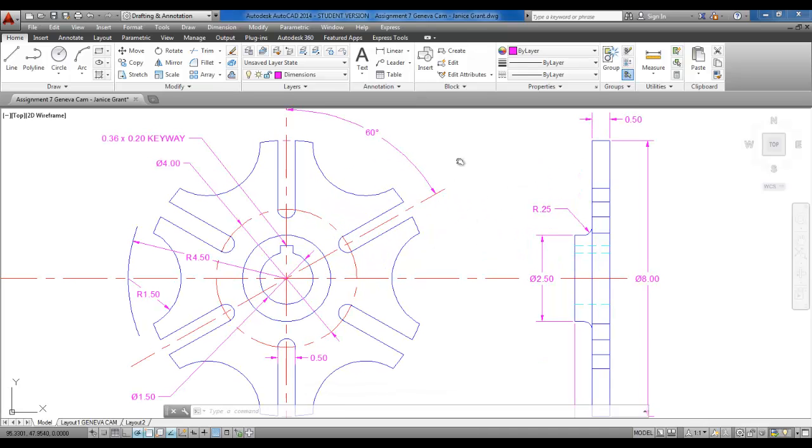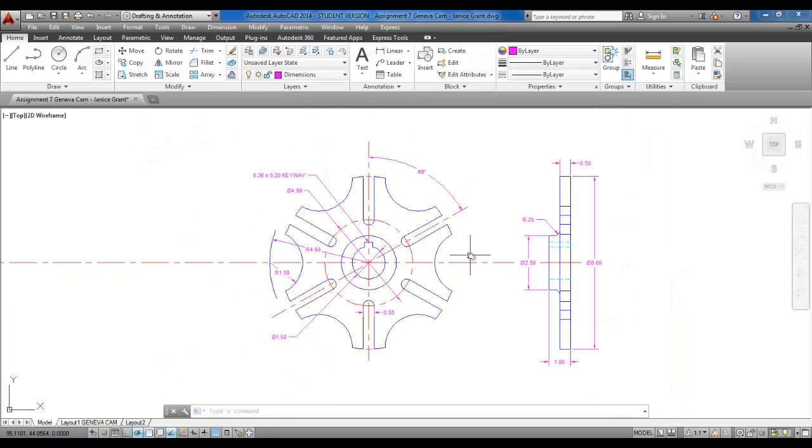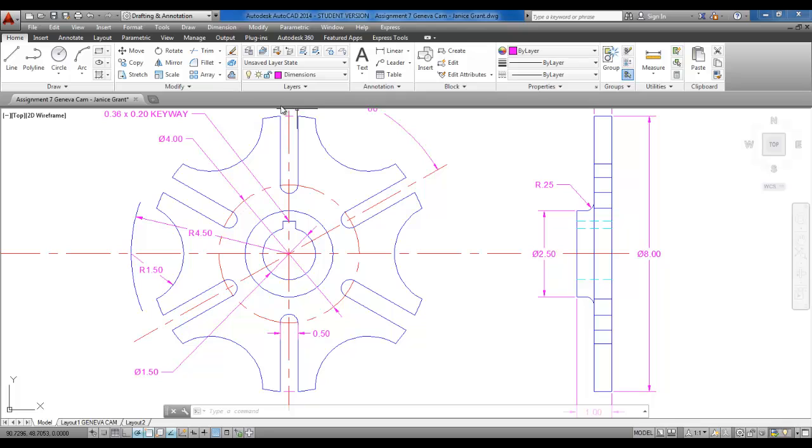So you'll need to probably go back and create another 8-inch diameter circle so that you can start this top line from right here, this intersection of the circle, and not these two pieces. And technically there would be another 2 lines that would come across here at the top. The book doesn't show those, but they would actually be there in that view.